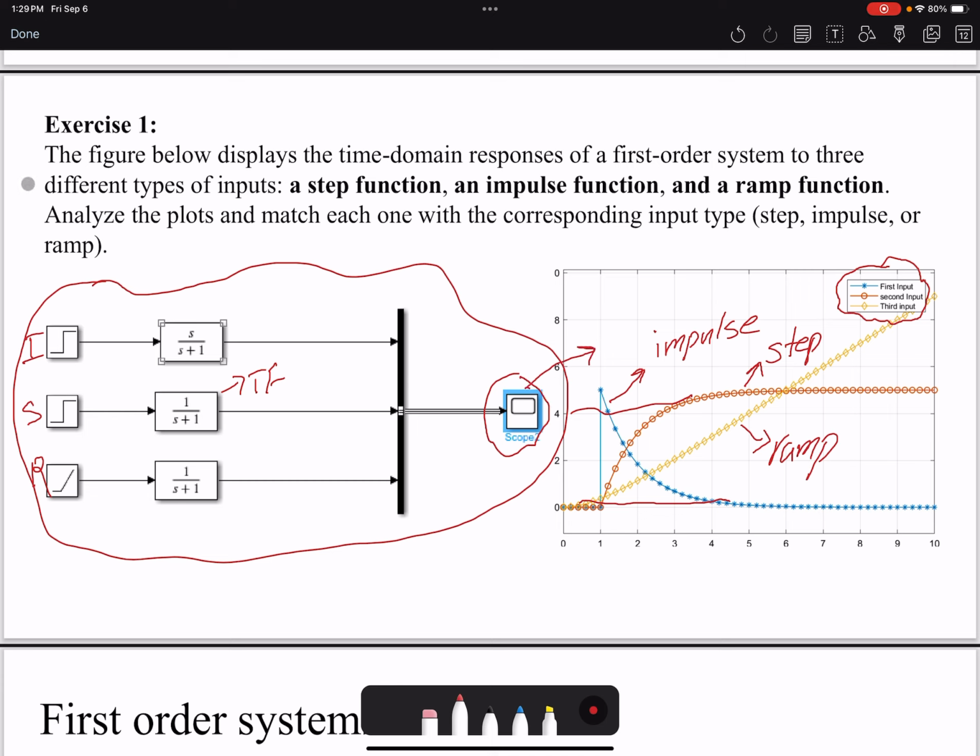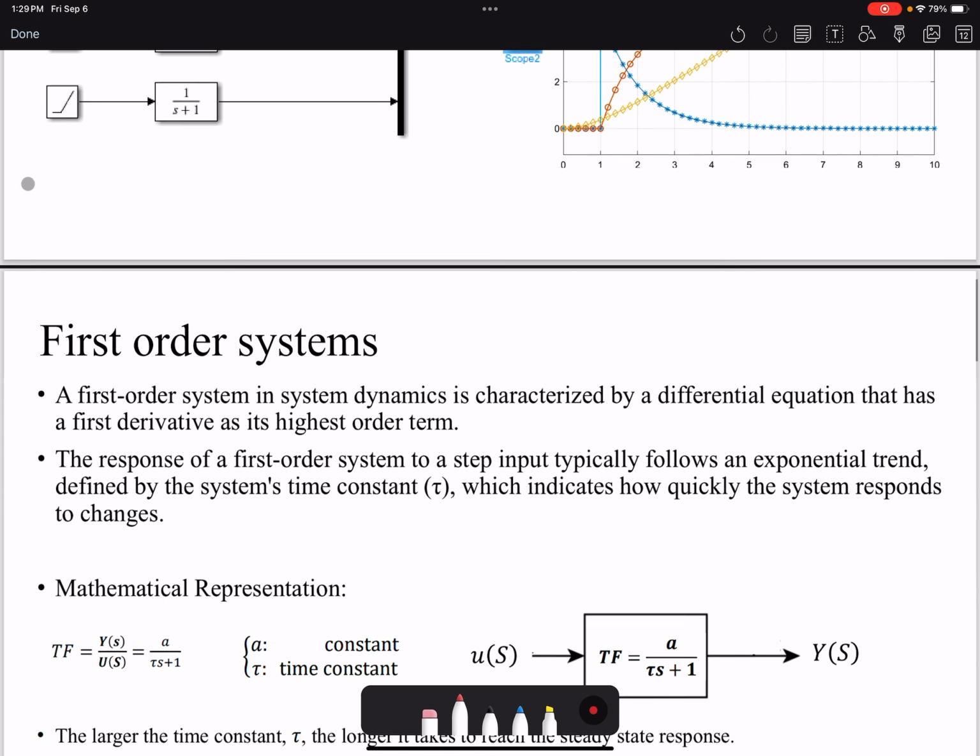One thing that you need to pay attention to is that MATLAB does not distinguish between impulse and step. We use the same function for both. But manually we are applying s in the numerator of our transfer function whenever we are talking about impulse, because you're just going to remove the effect of that step and then have it as an impulse.